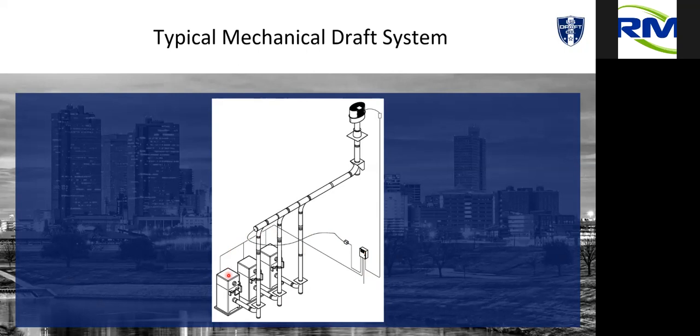Once that's done, the boiler will go through pre-purge. By code, that appliance has to do an air turnover 3 to 5 times in the appliance before it's allowed to even try to fire. And that's to make sure that any residual flue gases that remain from the previous cycle have been evacuated. So that boiler turns the fan on to pump as much air as it can through its boiler as quick as possible. That's going to affect pressure here, which means my fan is going to react.